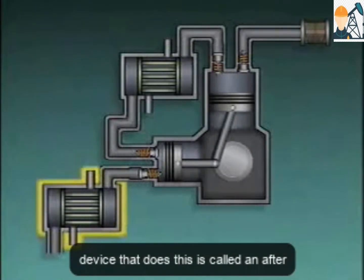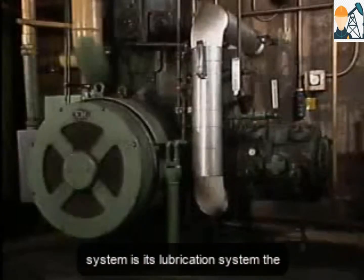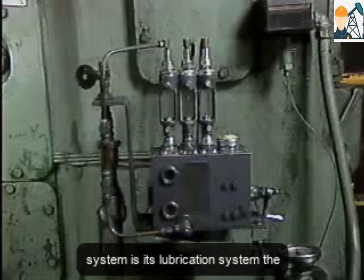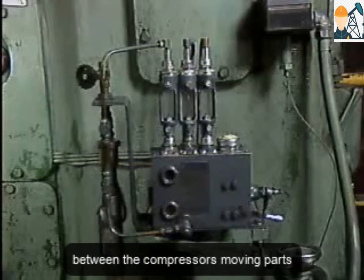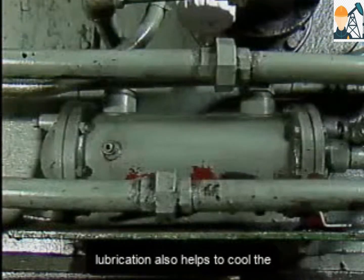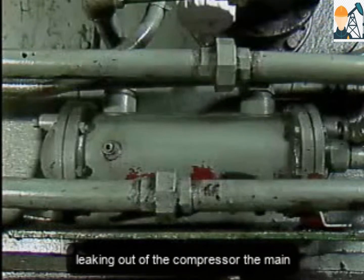The device that does this is called an aftercooler. Another important compressor system is its lubrication system. The main function of a compressor's lubrication system is to reduce friction between the compressor's moving parts. Lubrication also helps to cool the compressor's parts and to keep gas from leaking out of the compressor.